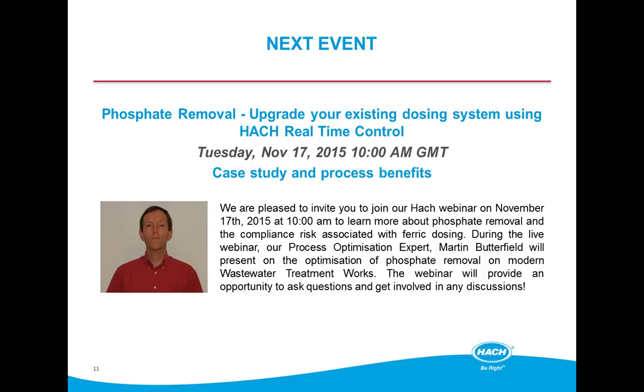And this is why it's important for us to speak with the operators and actually gain that experience. So we kind of hold the operator's hand through the commissioning period, and often, if a plant's been run at, say, 2 milligrams per litre for 10 years, when you mention that the plant can run at 0.7 or 0.6, eyebrows are raised, and there's the sort of disbelief, oh, this will never work.